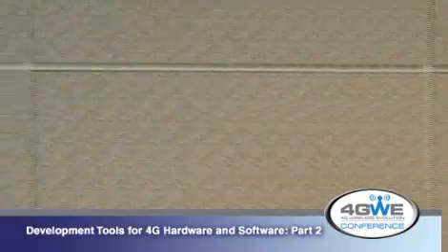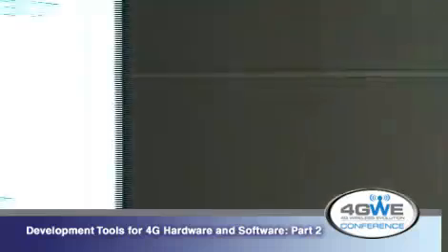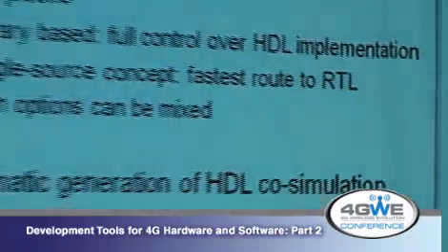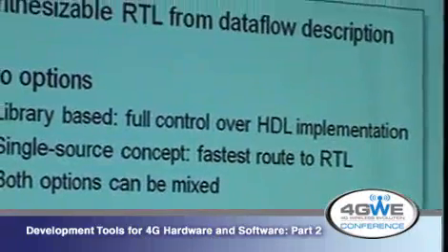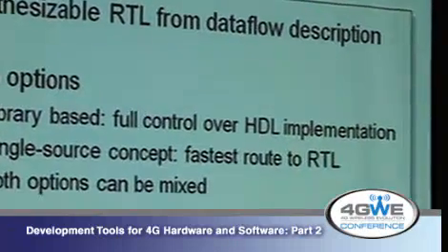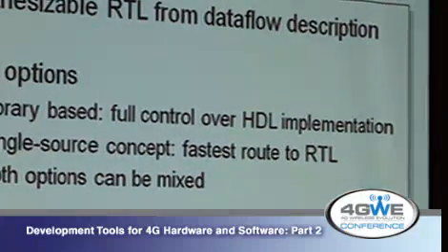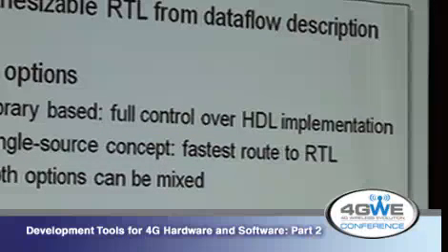And then in an ideal world, but we are not quite there yet, users are asking for automated RTL code generation, just like Tensilica, as Chris pointed out, is giving you as one of the deliverables at the end the RTL of the processor together with all the software tools you need specifically for this processor. People would like to have for the hardware components, and Chris was pointing to that with the TIE extensions, the Tensilica instruction extensions, and the hardware components being able to generate out of this. People would like to do this for general hardware accelerator blocks as well.